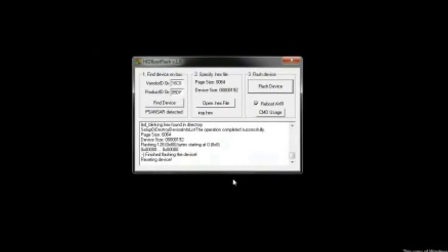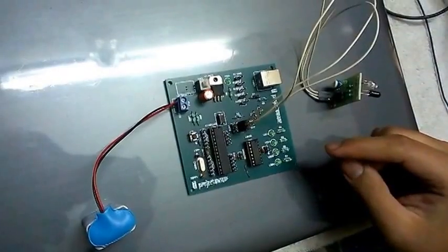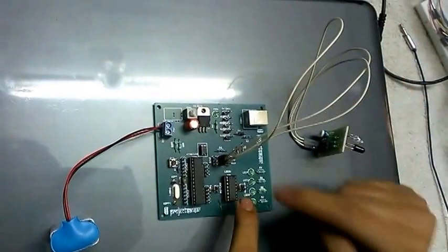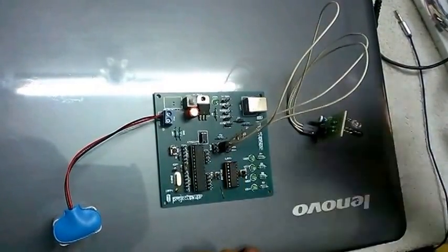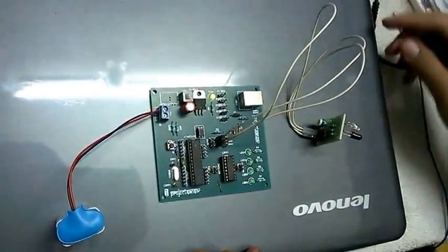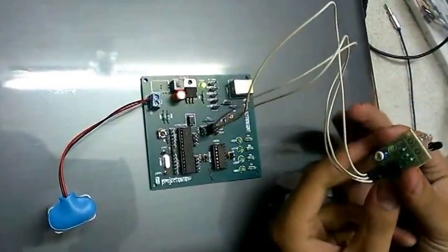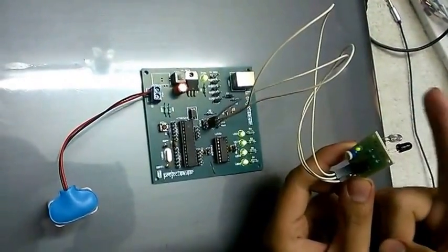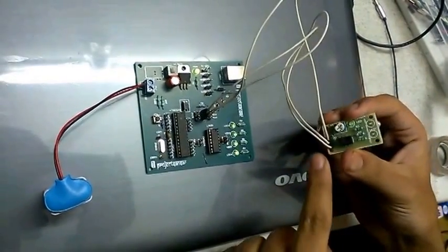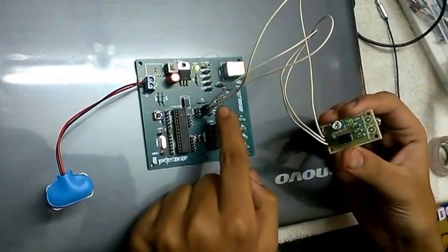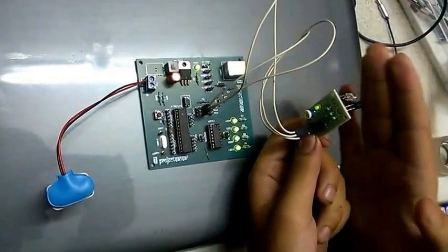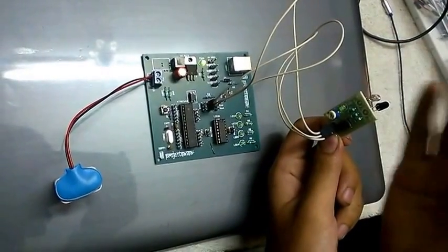Sometimes you might even see an output without the sensor connected. That is because of the microcontroller board floating. So here we have made the connection. This is the sensor 2, which is connected to the PC1. We switch it on and we check our program. So whenever an obstacle comes, the LEDs glow. So we have connected this VCC to VCC, ground to ground, and V out to V out. So whenever an obstacle comes, the LEDs glow.